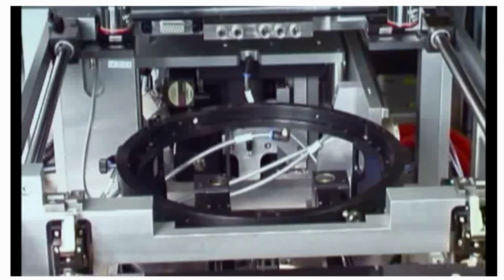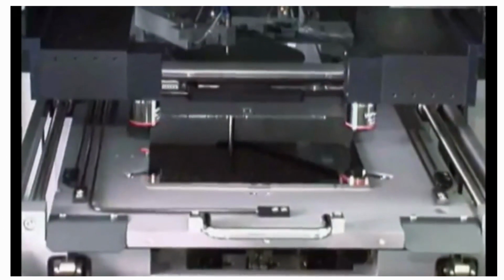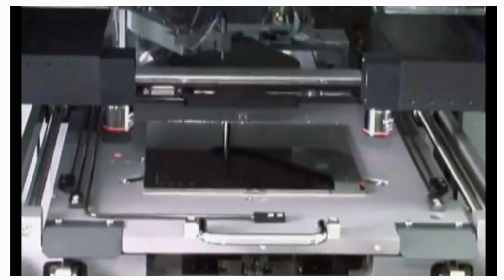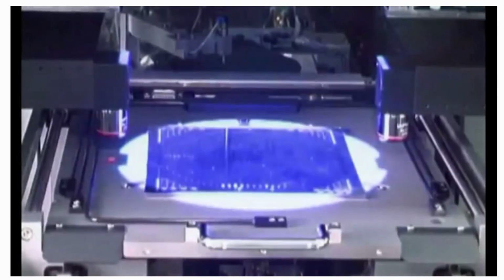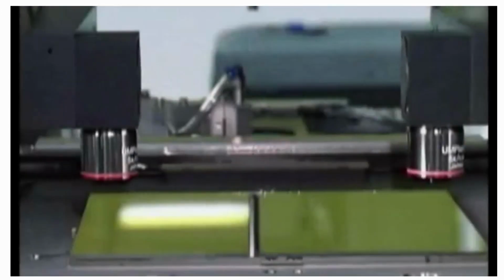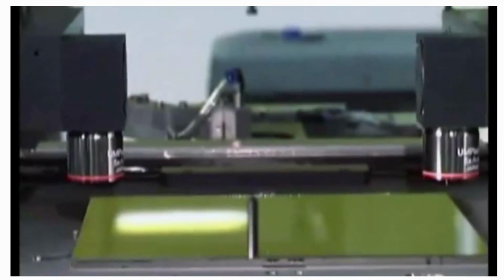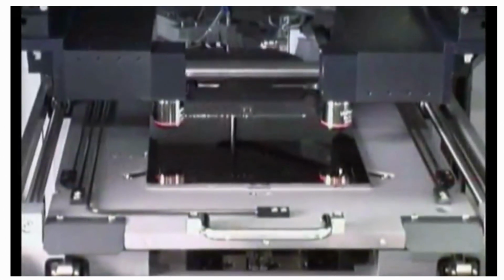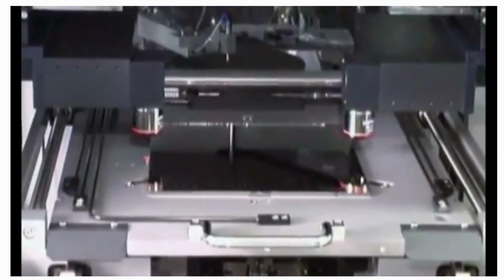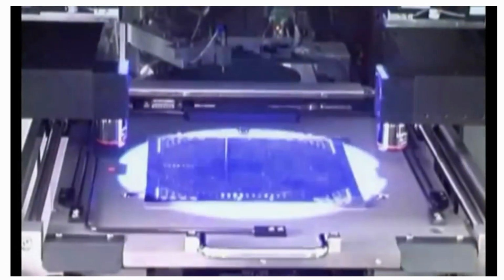Because of the MA200 Compact's newly designed microscope, during exposure, the mirror housing doesn't move forward. The microscopes only move sideways, thus reducing the vibrations of the alignment stage to a minimum, resulting in far greater accuracy. The optics of the MA200 Compact are optimized for thick resist processing. In thin resists, it achieves a resolution of 3 microns in proximity mode and a sub-micron resolution in contact printing.